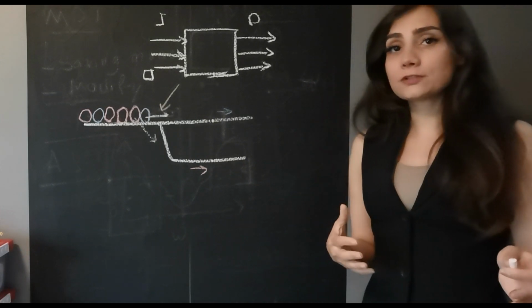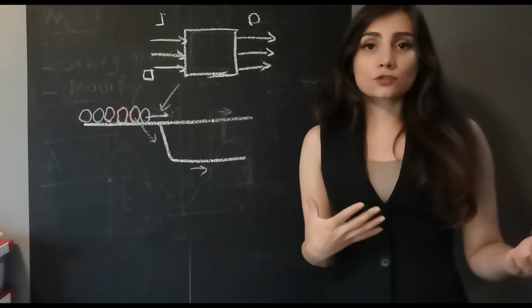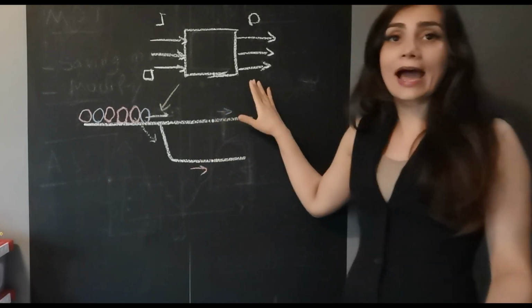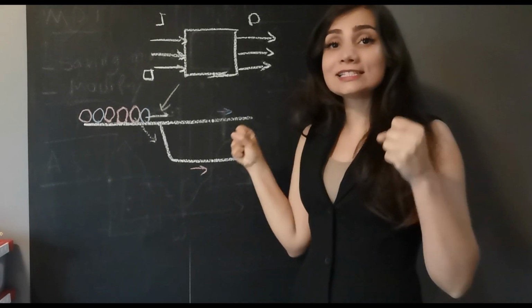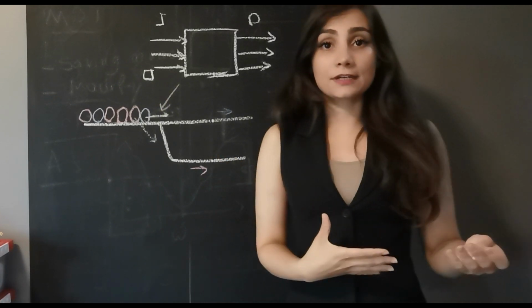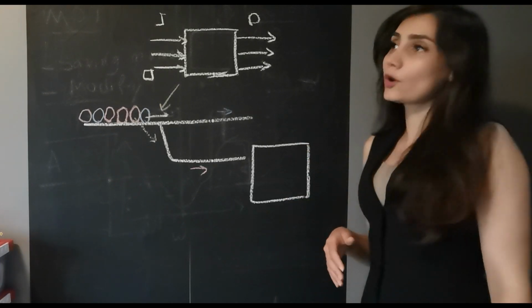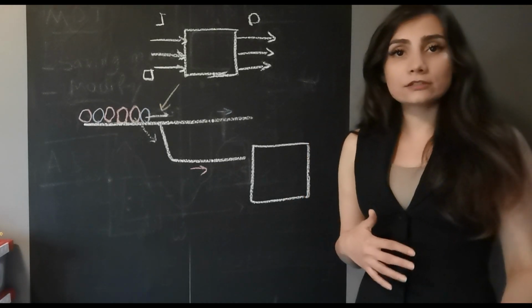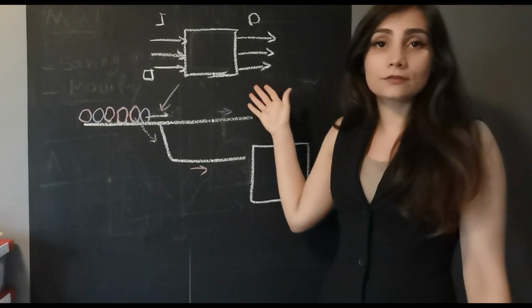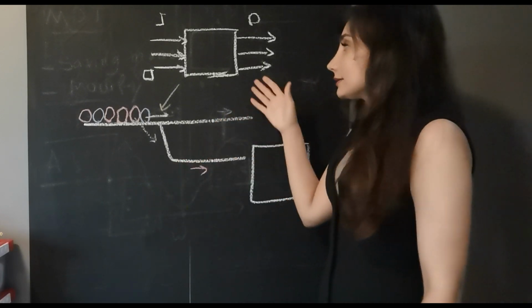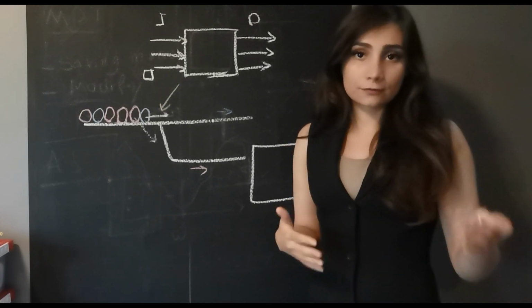One of the things that we have to keep in mind is that this controller, the PLC itself, for sending a signal, doesn't need that much voltage. But then some of the actuators that it has, for example, a very big motor, require a different type of voltage. In order to protect the system, they isolate these two circuits. You have your circuit isolated, which is very important actually, because if you are working in an industry and some of these actuators use very high voltage, if something goes wrong, then your PLC is not going to get destroyed because it wasn't actually in the circuit of the high voltage.